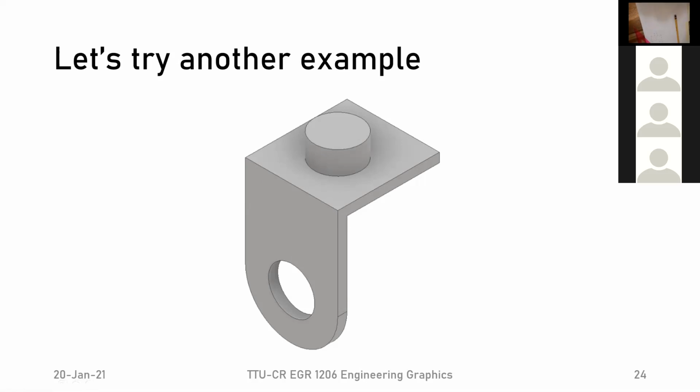It's the same as this edge here. If I think about my object as looking like this, if this were now my front view, so I'm looking through this object, then I'd be able to see that this line exists. Does it make sense? The same way that we did when we said we're looking at our object in this way, we were able to see that this edge exists because we can look through the material to see that edge. So that's what this dashed line is. That's this hidden line, I'm sorry.